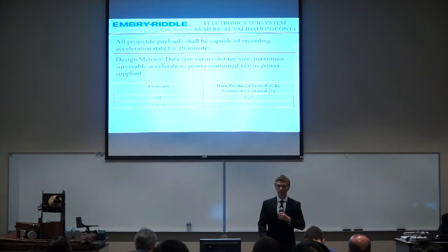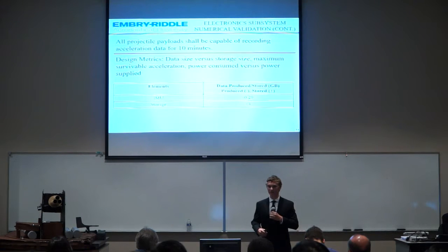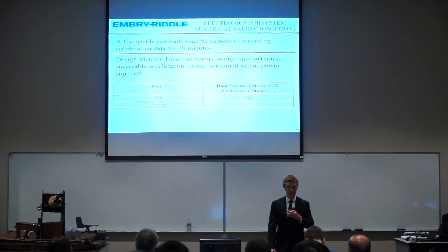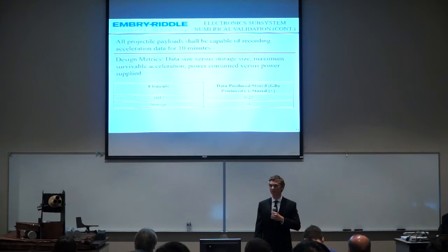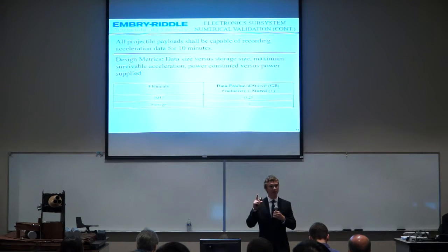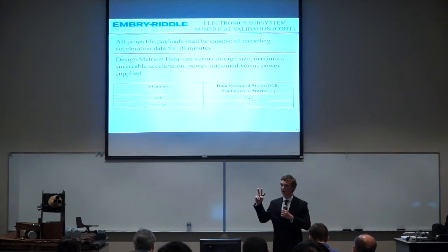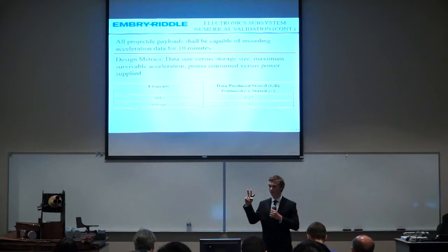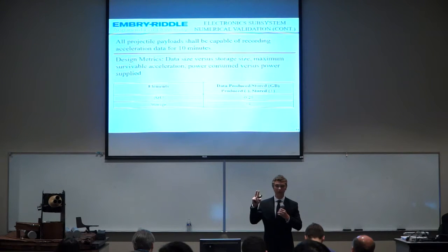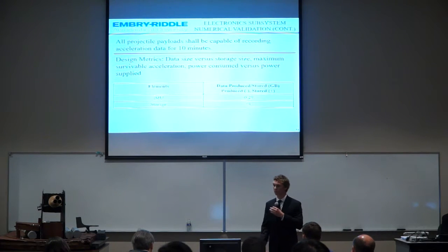All projectile payloads shall be capable of recording acceleration data for 10 minutes. For this one, we have 3 design metrics. The first is the data size versus data storage. This ensures that we can store all the data that is collected in those 10 minutes. The second is the maximum survivable acceleration. All of the electronics on board the projectile payload need to survive the impact. And thirdly, the power consumed versus power supplied. We need to be able to provide enough power to all of our electronic elements for this 10 minutes in order to be able to record acceleration.